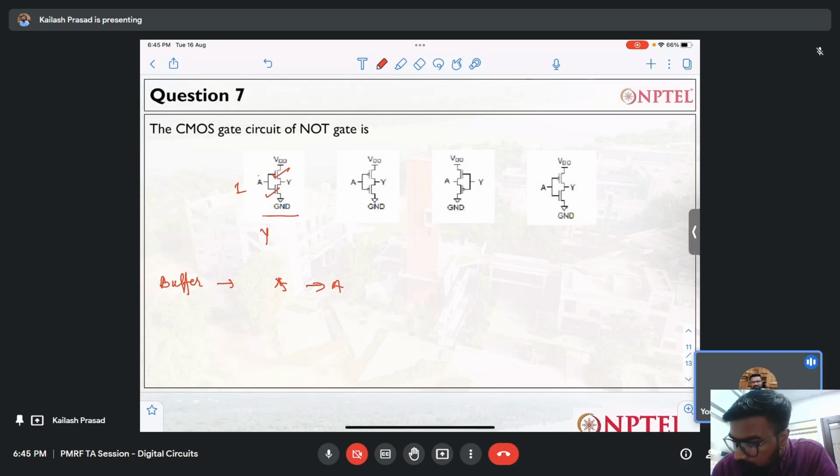So the voltage you will get here, if I treat both the transistors in a similar fashion, will be near VDD by 2. I'm writing this expression as nearly VDD by 2, because from the top VDD will be coming and from the bottom the ground will be coming, so the voltage will be something in between. It is in the indeterminate range; we don't know the answer. As digital designers, we don't work in VDD by 2.